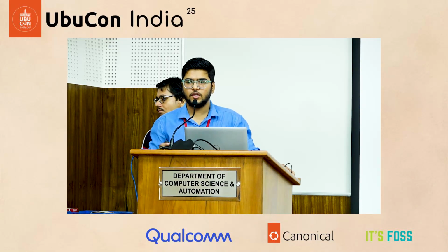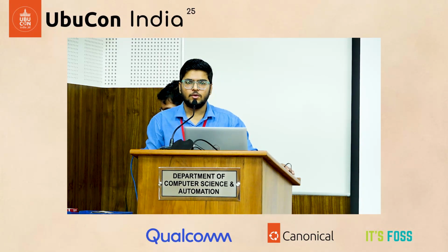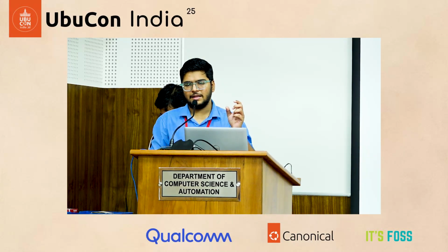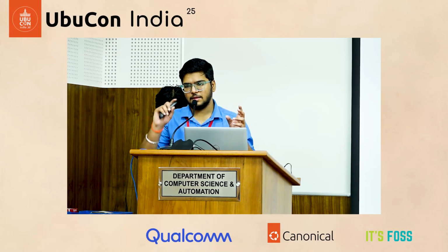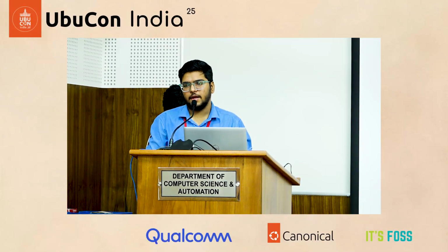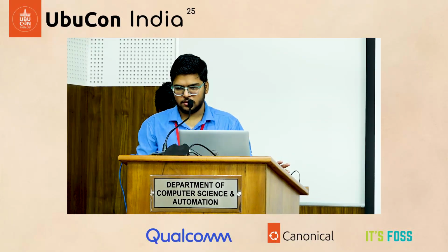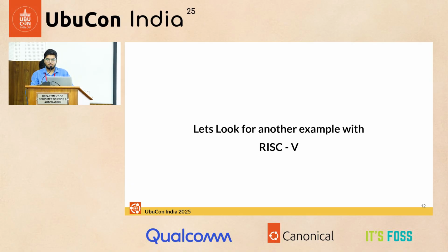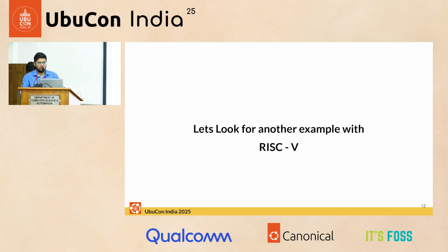And if your circuit is very complex, at that time you can take that circuit as a block, and the block is called a subcircuit. So inside, everything is there, only to add these things to the main workspace. The video demonstrated this for analog kind of things. If someone wants to build something from the transistor level, adding transistors, resistors, everything, then you can follow the earlier video.